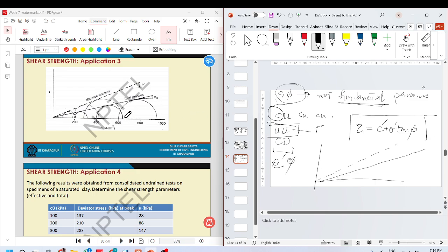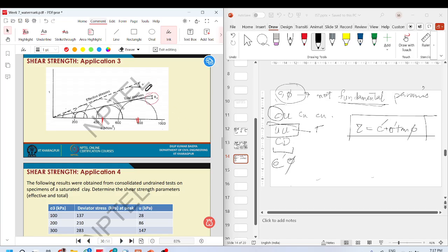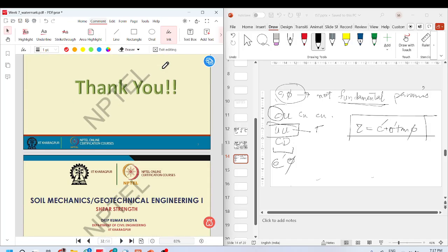This does not mean that at different stresses, strength of the soil is different. It just means that the locus of the Mohr circle will be different, leading to a flatter or a steeper slope. So you see, same tests will have same Mohr circle. Only difference is that you will have a different locus for the center of the Mohr circle. The radius of the Mohr circle will be same. So this is the undrained total stresses. These are the drained effective stresses.